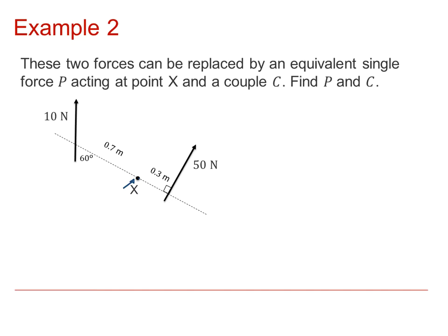We can use any two directions we wish, but one obvious way would be to use the line which is on the diagram and the perpendicular, so that the 50 Newton force is in the line of the perpendicular, and we only need to then look at the 10 Newton, which will have components of 10 cos 60 along the line on the diagram and 10 sine 60 on the perpendicular.